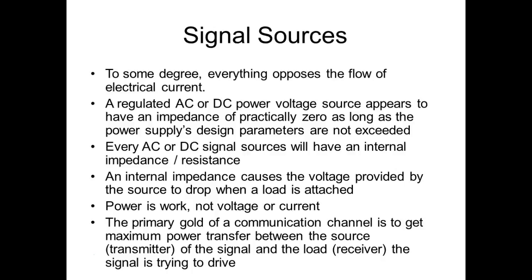You understand? And this is what gets us in trouble, because when the wire starts heating up, its resistance goes up. The regulated power supply just adds more energy because it's trying to get back up to its regulated value. Does that make sense? Yeah, so these regulated power supplies, these guys are the ones that burn stuff up. So the resistance goes up, the voltage goes up. The resistance goes up, the voltage goes up, and it pumps it into that short, it'll burn stuff up.